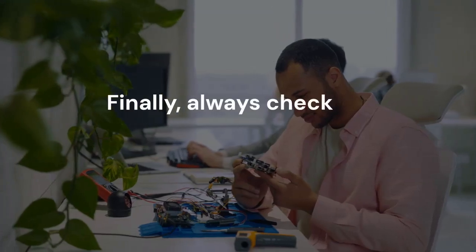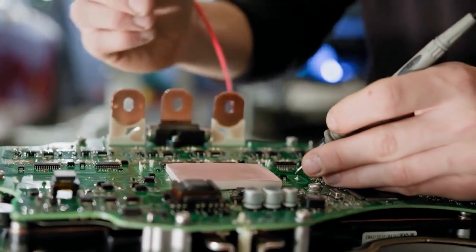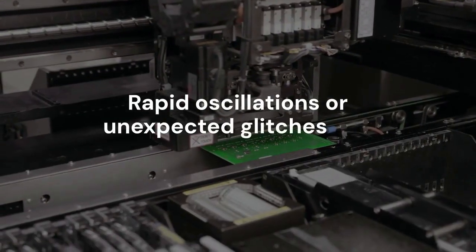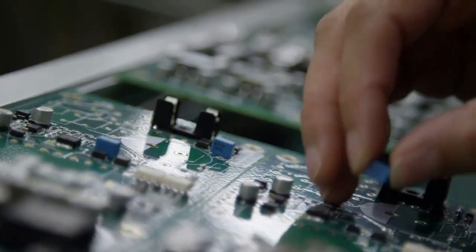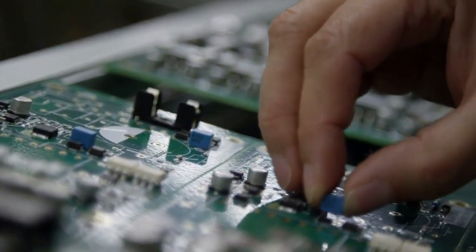Finally, always check for oscillations or glitches in your circuit. Sometimes, the excessive CPU load error is a symptom of an unstable circuit. Rapid oscillations or unexpected glitches can overload the simulator. Carefully review your circuit design for stability issues. Look for floating inputs or potential short circuits.